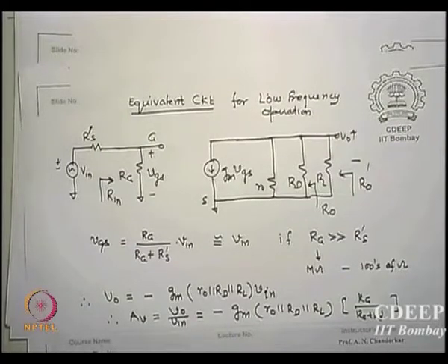Typically R0 is of the order of mega ohms, RD is of the order of few kilo ohms, tens of, 20 kilo ohms. So the actual output resistance can be taken as RD. So the output resistance of a MOS amplifier in a common source technique is just the drain resistance which I apply, and that drain resistance decides what?